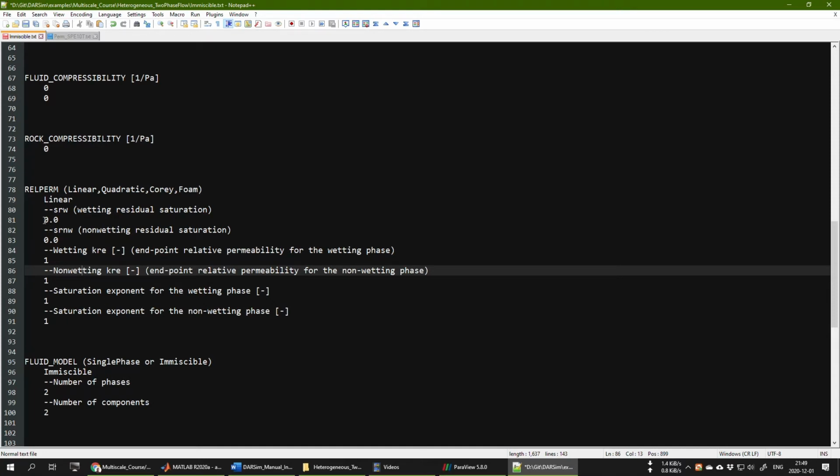Make sure that you give the values underneath one of these examples, in such a way that if linear is at line 79, this keyword or option is at line 79, the first value is 2 lines below, so 81, and then 83, and then line 85, line 87. This is how the simulator will run it, and this is useful because on the line above you can have an explanation of what every parameter and the value underneath it means.